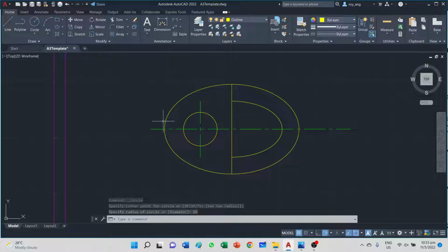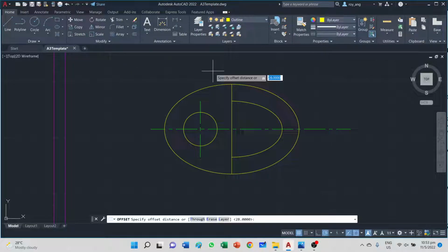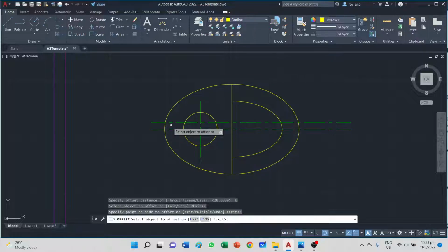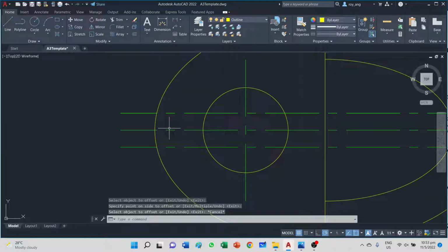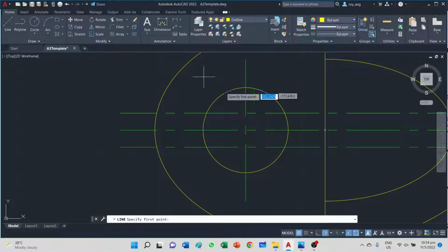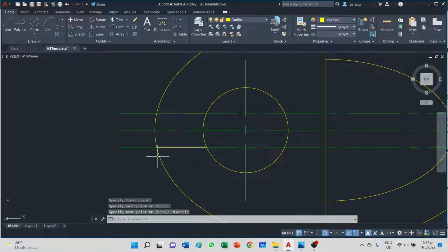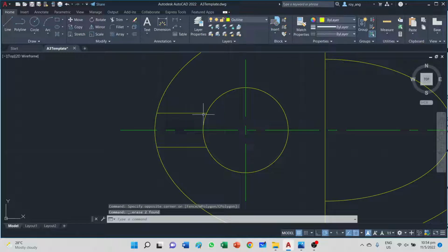And there is a slot, and the slot width is 12 millimeters, but we all know that because it's in the center, so it's 6 millimeters on each side. So what you can do is you can put it both. Whoops, I think I did it too fast. Yes, 6 millimeters on each side. So I make use of the center line as a construction line. I haven't changed the layers yet. Okay, and then I delete away the unnecessary lines.